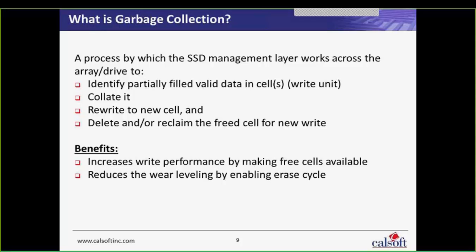So basically wear leveling deals with a process that is designed to extend the life of your storage devices. Normally a storage block or a cell has a finite number of program or erase cycles before it really becomes unreliable. For example, a single cell NAND flash is typically rated at about 100,000 program erase cycles. So wear leveling is an engine which basically arranges data so that write erase cycles are distributed evenly among all the blocks or all the cells in the device.